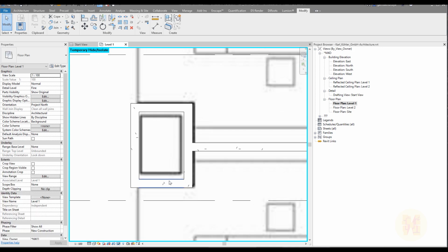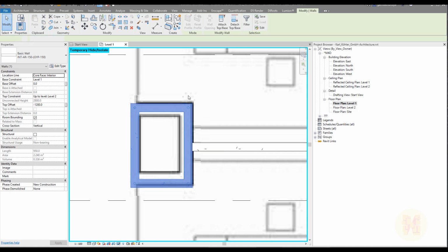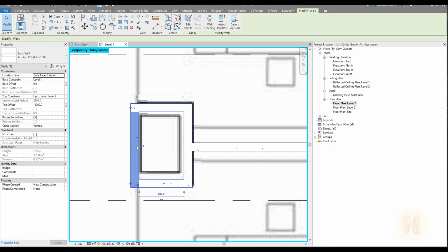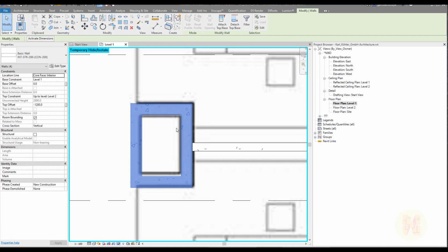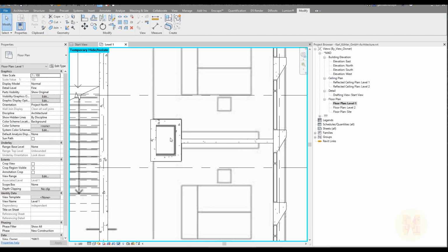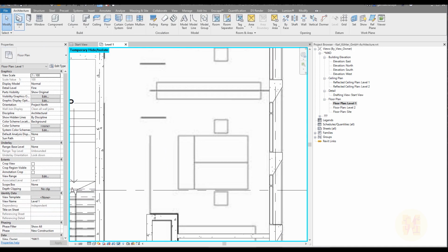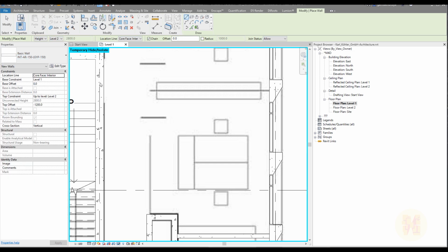Actually, we should change here the type of the wall. Let's use the Tab key, and now we'll loop all this wall. Just select your wall, click the Tab key, and you can now select all the looped walls. Let's change the interior to the structure, because actually this is structure. As I said before, all the construction that covers your shaft is a construction part; it's impossible to make it gypsum. Architecture, wall, and let's change our wall back to the interior architecture one.